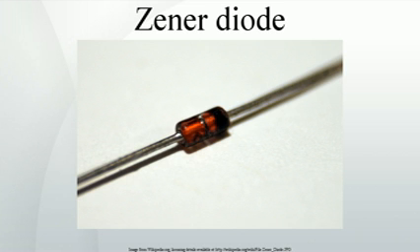Surface Zeners. The emitter-base junction of a bipolar NPN transistor behaves as a Zener diode, with breakdown voltage at about 6.8 V for common bipolar processes and about 10 V for lightly doped base regions in BICMOS processes. Older processes with poor control of doping characteristics have the variation of Zener voltage up to ±1 V, newer processes using ion implantation can achieve no more than ±0.25 V.